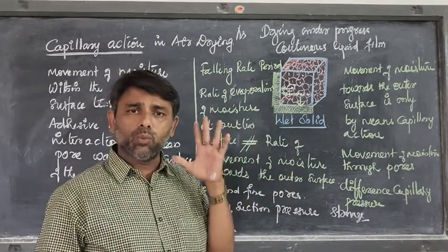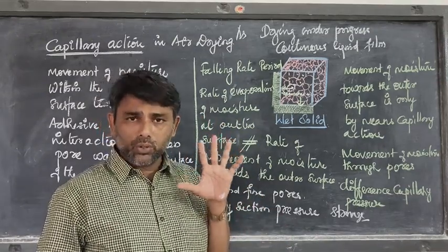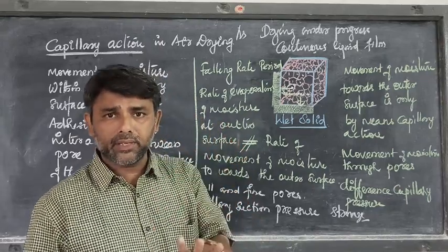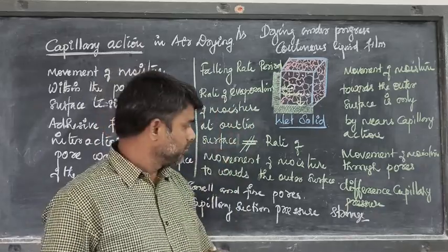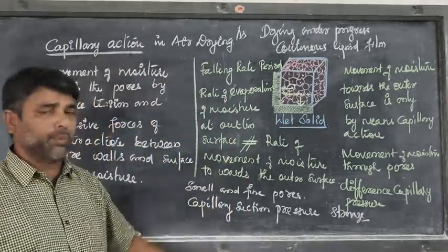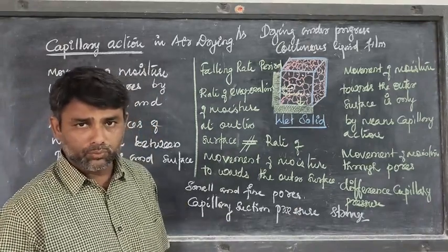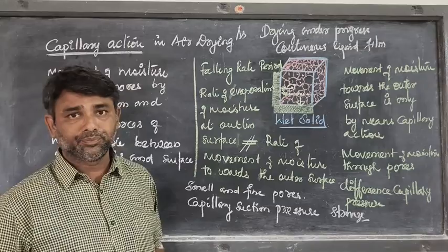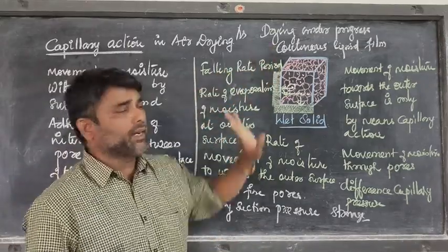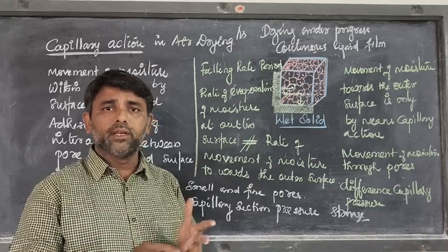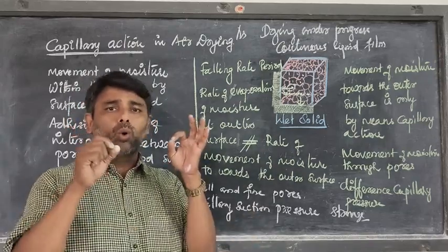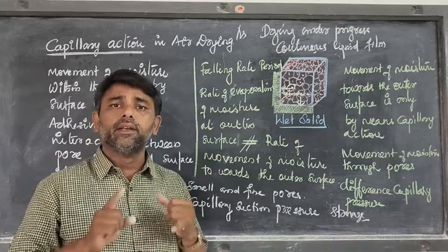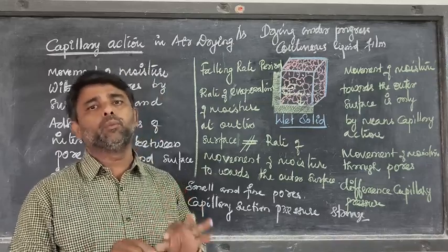For fine and very small pore structure, this difference in capillary pressure will be more, capillary suction pressure will be more. Clear? This is the fundamental behind the capillary action. Clear? As drying progresses, the continuous liquid film will be broken down at one fine point. From that point onwards, liquid diffusion and vapor diffusion will be more predominant.